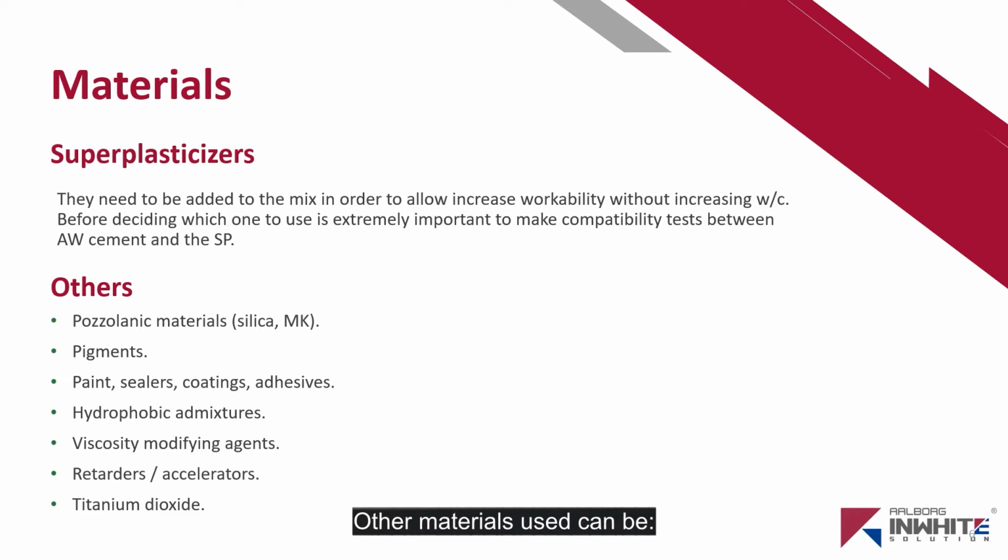Other materials used can be pozzolanic materials, silica fume and metakaolin, pigments, paint, sealers, coatings, adhesives, hydrophobic admixtures, viscosity modifying agents, retarders, accelerators, and titanium dioxide for the whiteness.